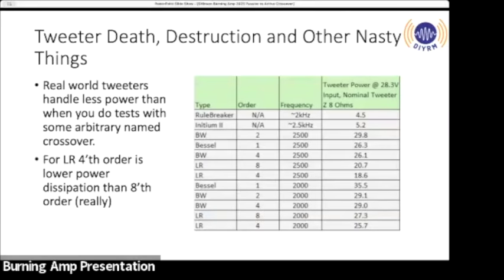go out, right? So the thing is that you should not be applying a named voltage function onto a driver in your crossover, because the driver has its own frequency response. And if you apply a Butterworth or a Linkwitz-Riley named filter on that, those two frequency responses add up, and you don't get what frequency response you want out of the speaker.